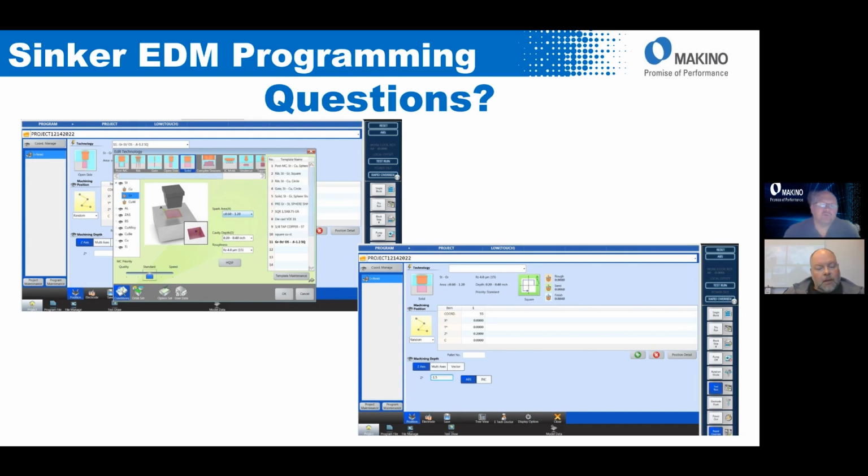Okay. So if you had an electrode like Juan's talking about with multiple small features on the trode, the good thing to do would be to measure the frontal area of all of the features that are going to burn. And then that would be the selection you would make during programming, and then allow the adaptive control to adjust as needed. Yeah, correct. That way, if they're not hitting at the same level when they start, the adaptive control will either jump more or add some of that off time to adjust, because we're starting on a small area.